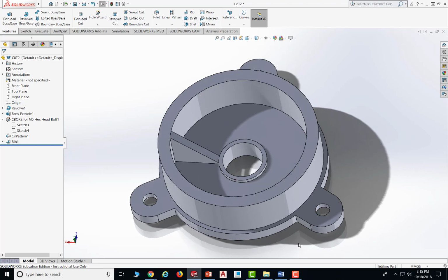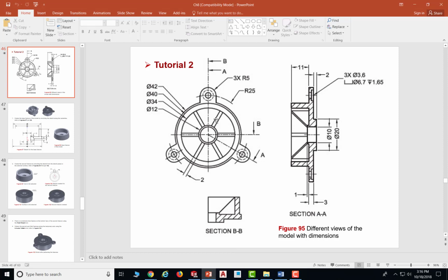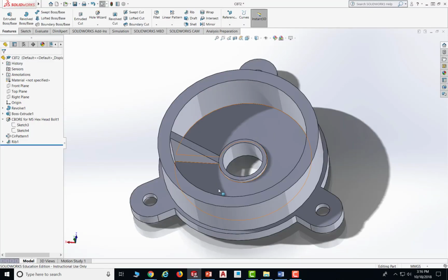Looks right to me. And now let's count the number of ribs. We have 1, 2, 3, 4, 5, 6. Okay, 6 of them. And yeah, you would need to select the front plane because this is on the front plane. Okay, so we will double check afterwards. So the rib is supposed to be here. So on the front, on this rib, okay, horizontal one should be 2 below and 1 above. So let's check, see if our ribs are right.